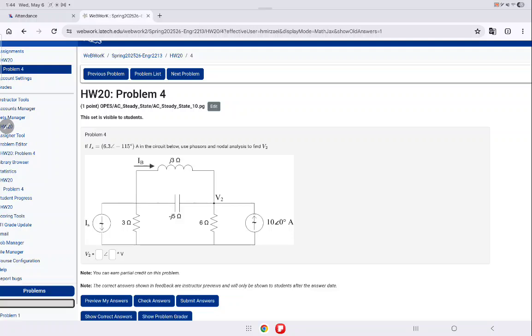Just to make you confused, do you see that IB? That's nothing. There's no mention of IB anywhere in the problem. Do you see that? They are not asking for it. There's no dependent source. So they just put it there to stop you from combining them. Don't curse me. I didn't do it. Okay? So just combine them because that will get rid of one branch. So combine the inductor with the capacitor.